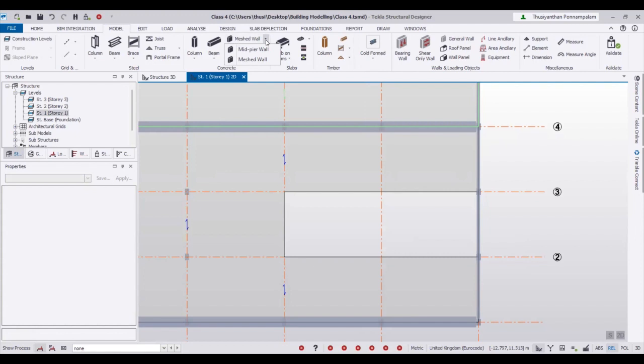Pier design and finite element, what's the difference, right? It's a big topic. If I go inside, I cannot finish it. Generally we do the pier design, but you can go with the finite element mesh design also, but it's not recommended. If you do the finite element mesh, then you have to be careful when you do the analysis and you have to look at all the peak stresses, right? Normally we do it only for certain very complex buildings, but for general symmetric buildings, we go with the pier wall system.